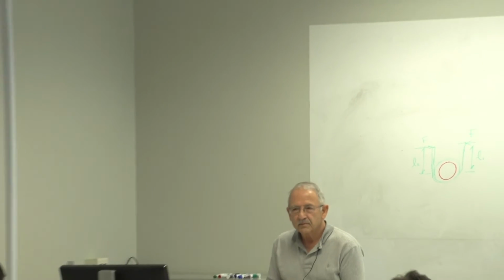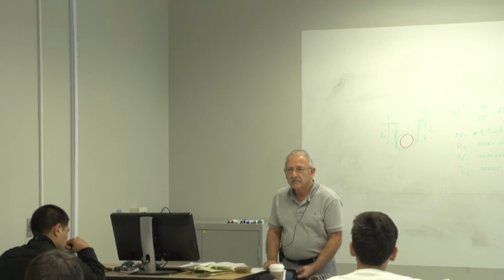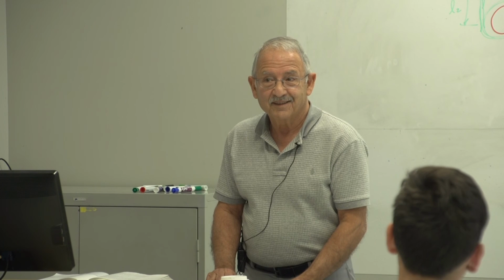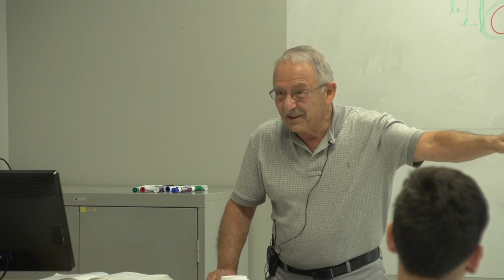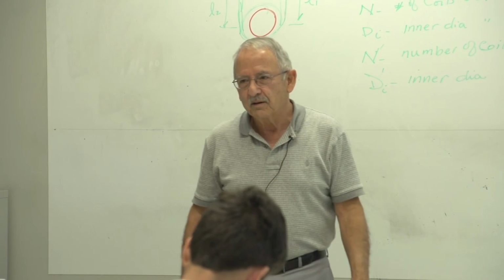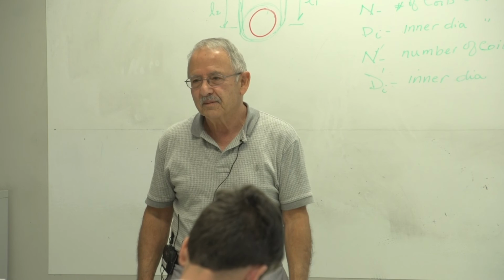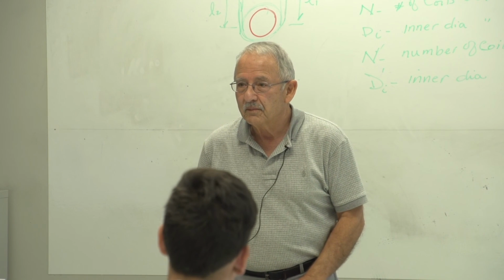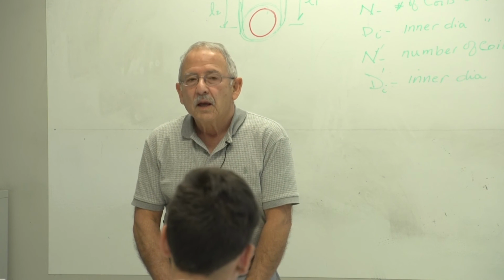In part A, you said Sy is equal to 0.6 SUT. I thought you said the range before was 0.3 to 0.5. That's for torsion. This is bending. And that's why I said it's low. Even at 0.6, it's probably 0.7, 0.75 is a better number than 0.6. Where was that information again? Which information? That scale factor in the book.